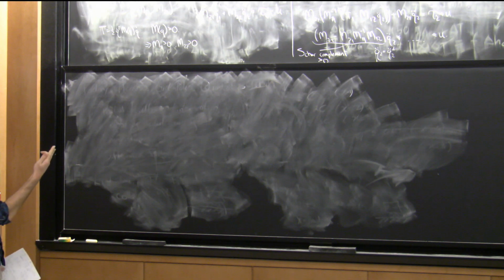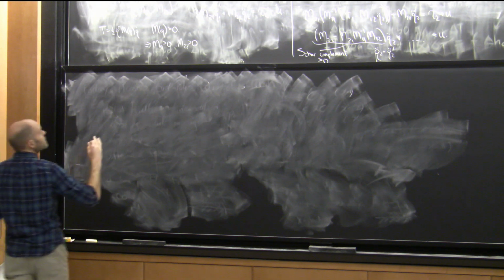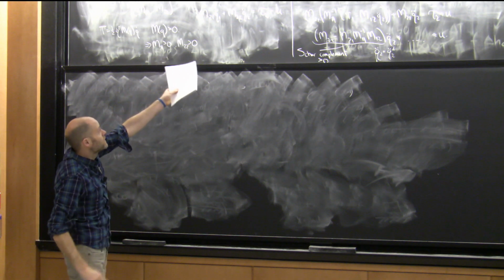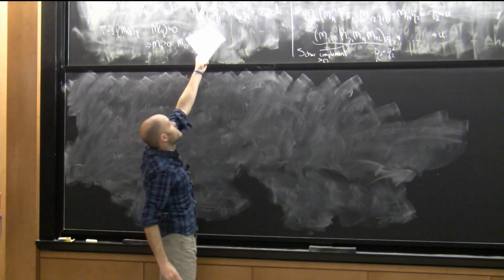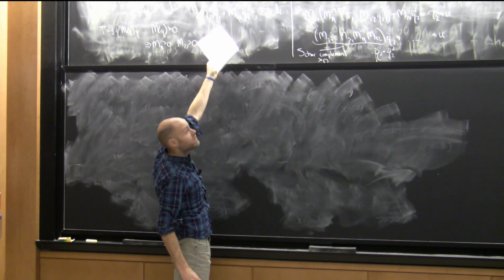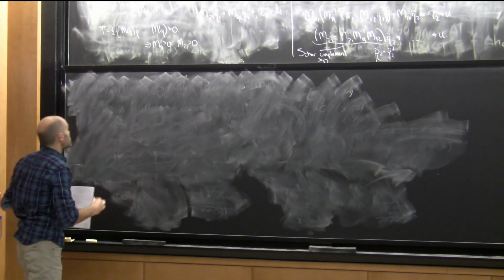The recipe is almost the same, but just the matrices that end up in these places are different, right? So the same thing. Now, if I'd like to control Q1, then I want this bottom equation to be only in terms of Q1. I need to solve away Q2. Okay, so let's solve that first equation for Q2.